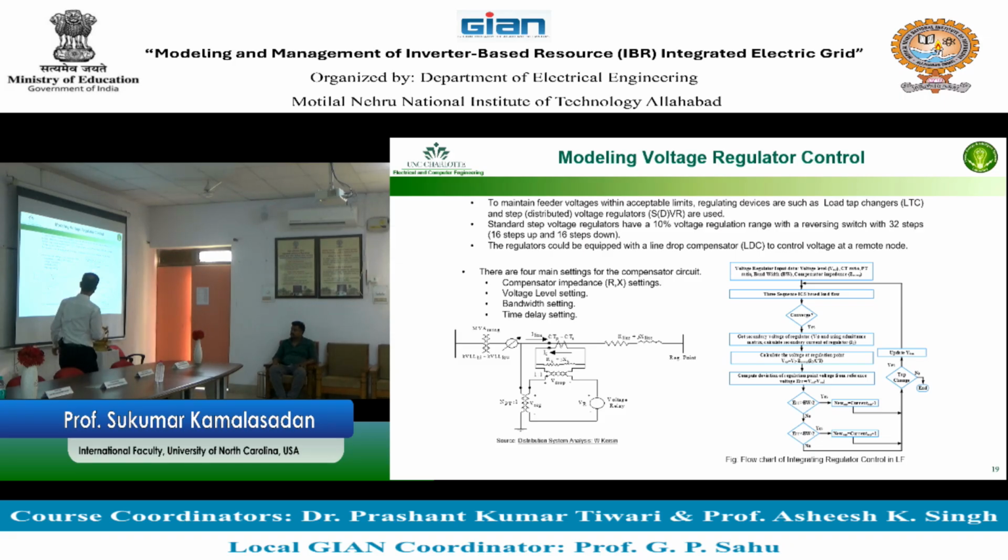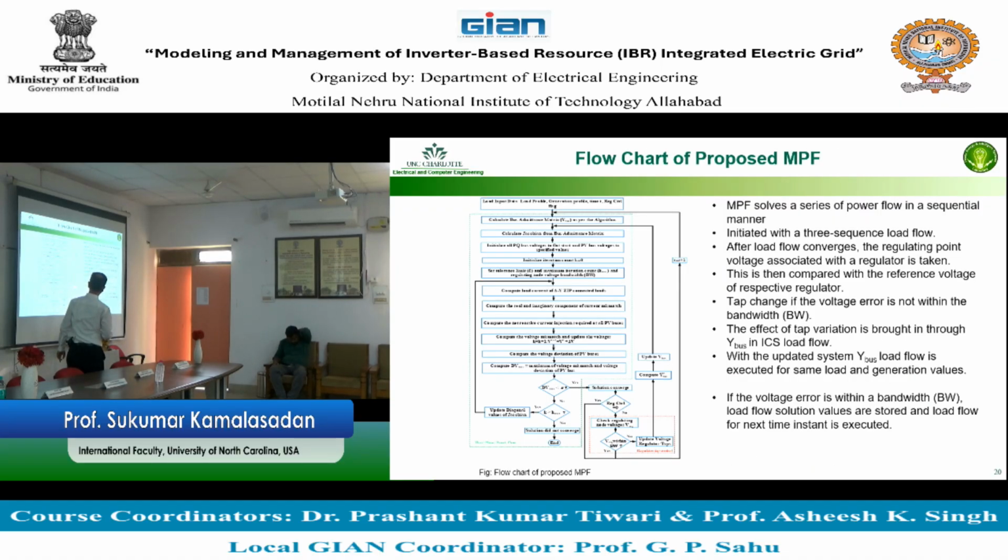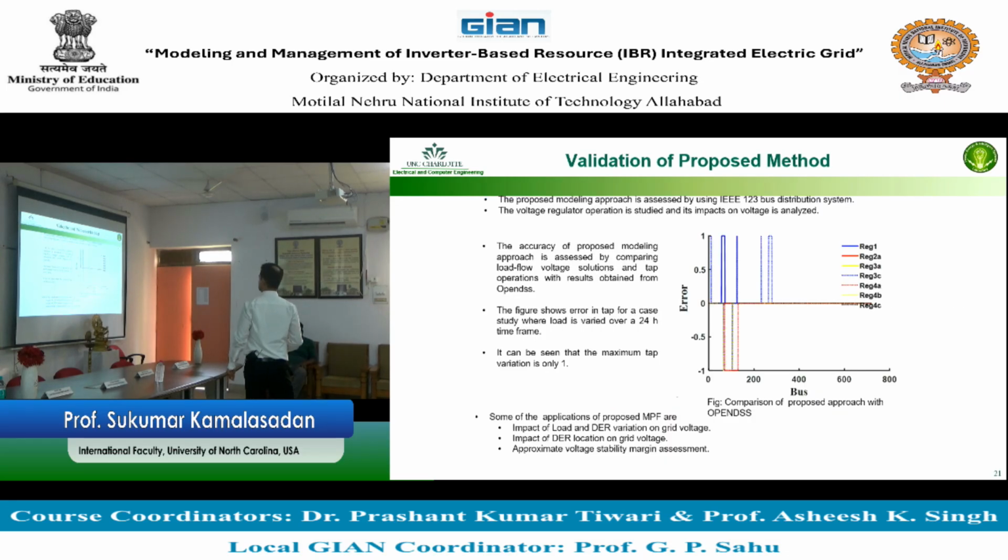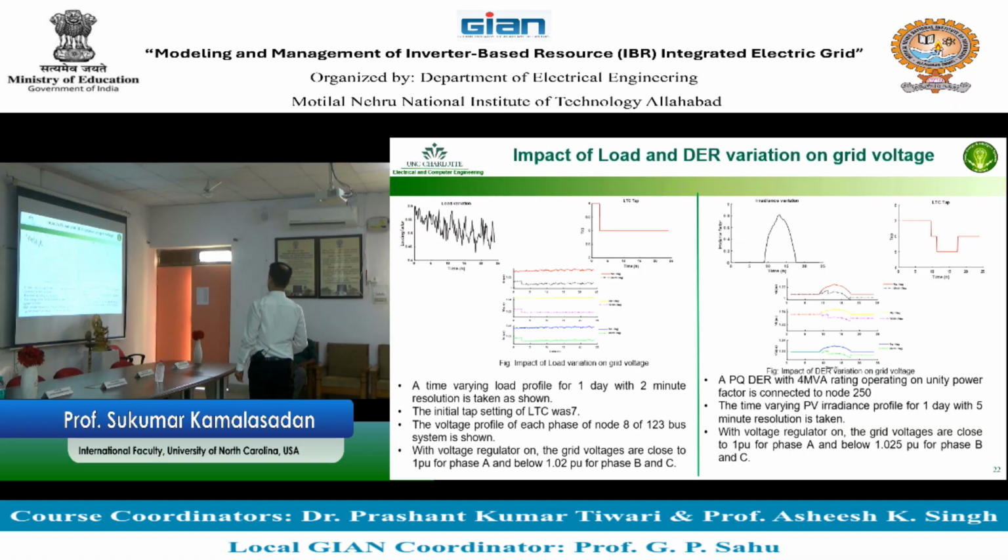So what we do is we make a model of this whole thing in the power flow, and you include that model of the transformer along with the power flow. What we did now is convert the power flow model into a time series power flow model. And these are some of the results. This is the result from the real model and the field device.